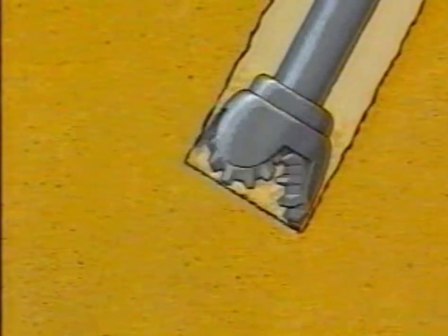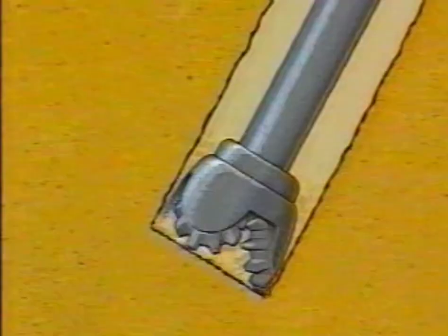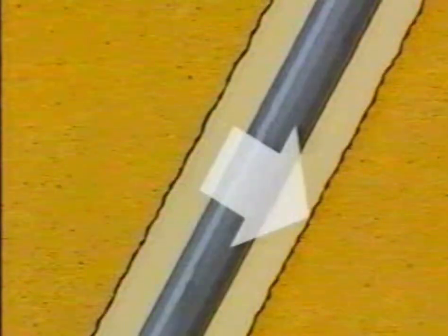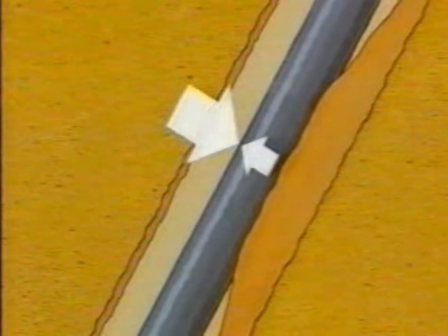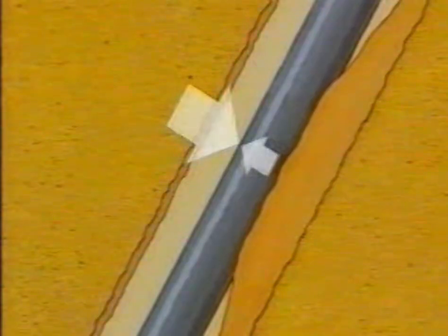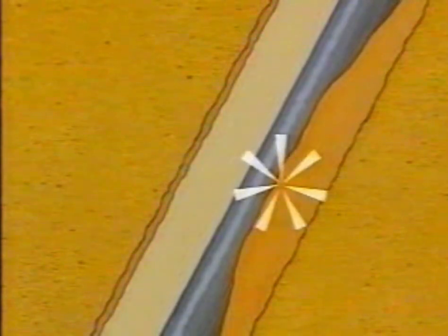When drilling through permeable formations, the pressure exerted by the mud column is greater than the pressure of the formation fluids. As a result, a filter cake will build up in the wellbore. Continual build-up of the cake will result in contact with the drill string. Any part of the string which is embedded in the cake will be subject to a lower pressure than the rest of the string. If the pressure difference across the filter cake is high enough over a large enough area, then the pipe may become stuck.